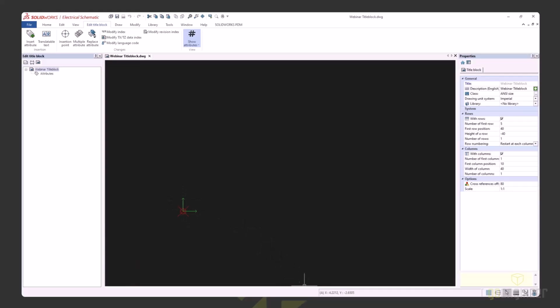You will notice that the origin is also being placed at the very lower right-hand corner here. If I select this position, you'll see that X and Y is almost 0, 0. Truly, if I were to snap directly on that point, it is 0, 0. The insertion point is also at 0, 0, and for title blocks, this is always where the insertion point should be.